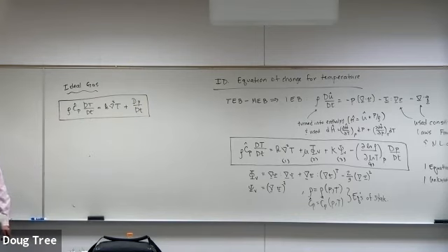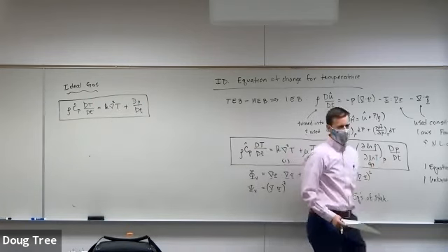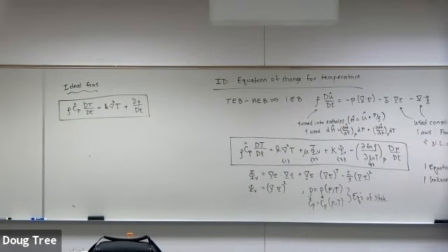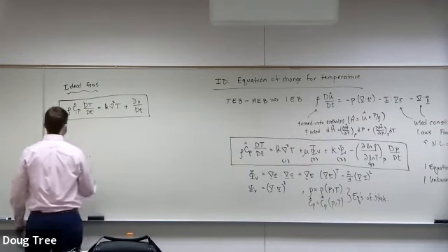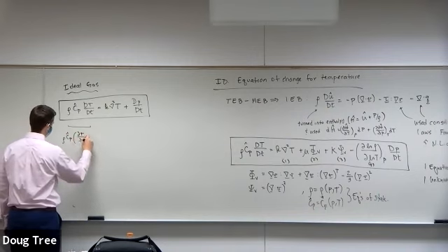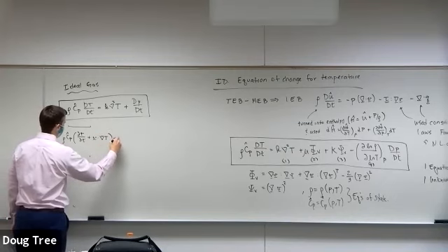Okay, so for an ideal gas, we lose these terms and we have that term left. And so if you look at that problem, when we solve one of these problems, and again, this will usually be for a compressible flow problem, we've got to worry about rho C sub P times dT/dt plus V dot grad T, right?